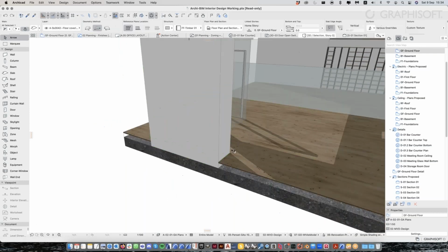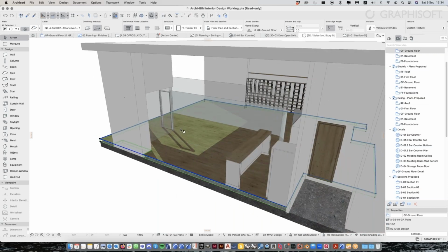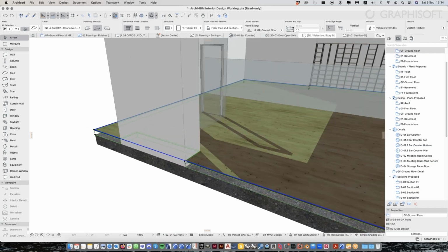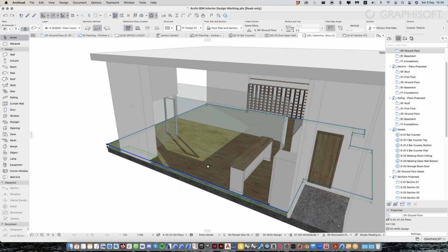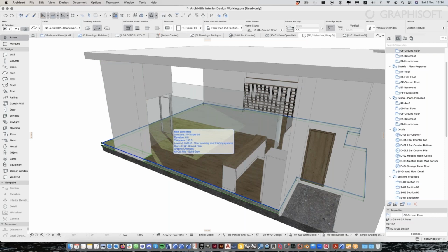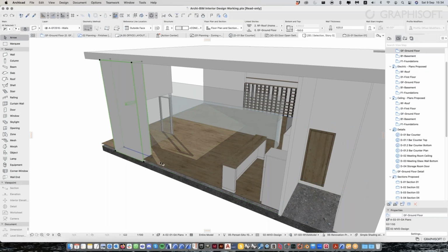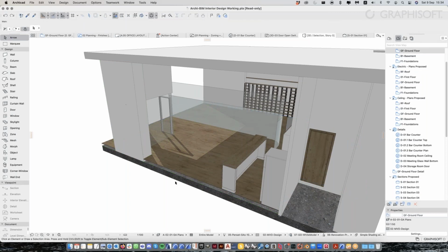And when you do need to extract the area of, let's say, the finished floors, you know that this part won't be counted even if you have modeled it like this. And so these are just little things, but I think it's good to know. And if you are getting more into this, it helps you to leverage the priority and be able to model and update things more efficiently. Okay.